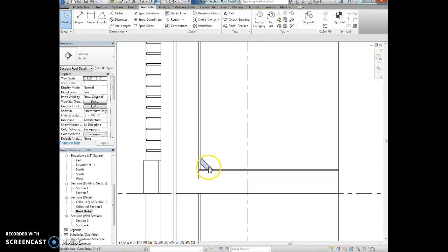And the purpose of this is so that water and leaves and some other things don't get stuck in the corner where the wall of the parapet joins with the roof. Right, so it's creating an angled piece. So now if it rains or snows, water will float down and away instead of getting stuck here and creating a potential leak problem.